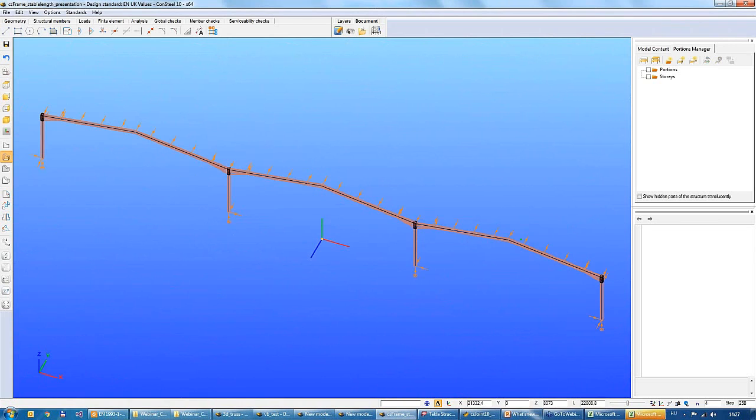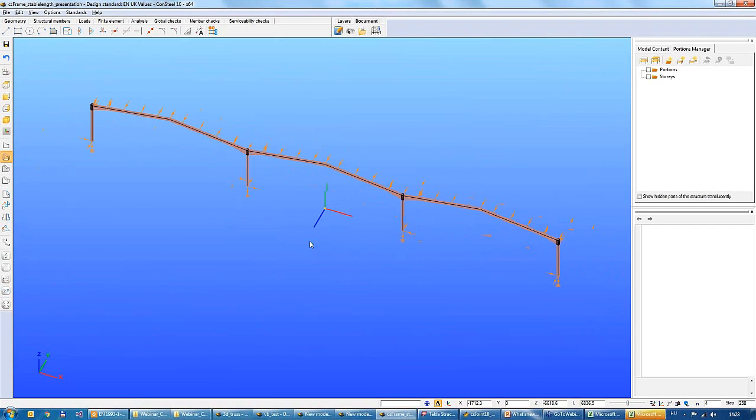This check is based on the results of the plastic hinge analysis, which was developed in ConSteel 9, and another key function for this stable length check is the frame corner wizard, which was also developed for ConSteel 9, and we have webinars on our official YouTube channel which present these functions, the frame corner wizard and the plastic analysis too. But right now I have brought a model.